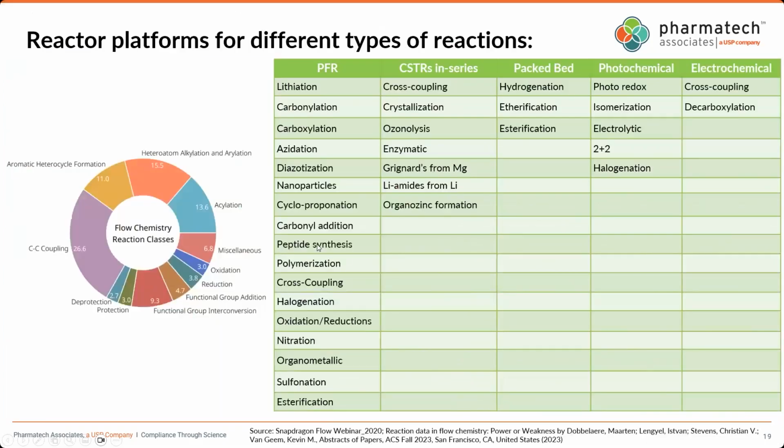No worries. I also think it's important to highlight, not just for the pumps but also for these reactors, that material selection is one of the big criteria in characterizing such a reaction system. Yes, absolutely. Because most of the API chemistry involves the use of corrosives and highly basic or acidic conditions. So the choice of the MOC also plays a crucial role in deciding what type of reactors can be used. So that's another good point here.